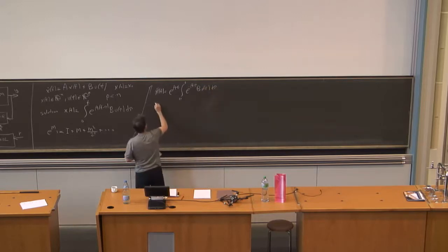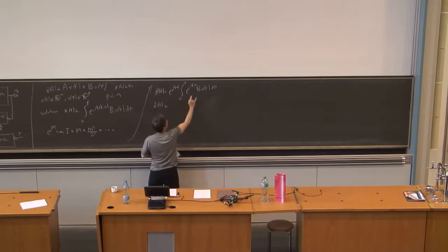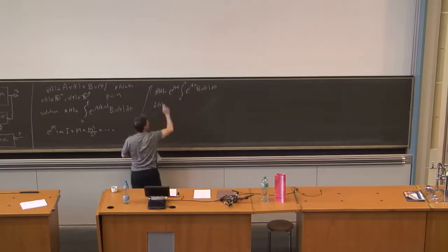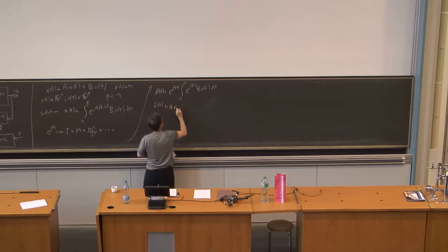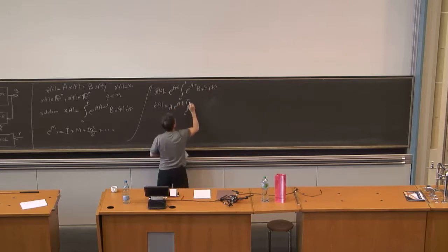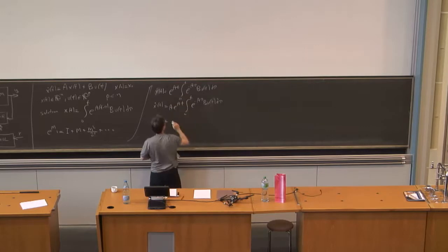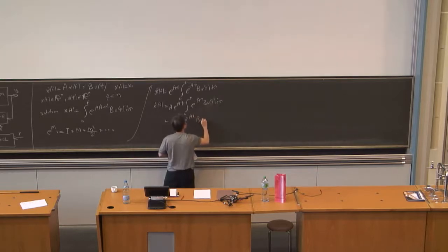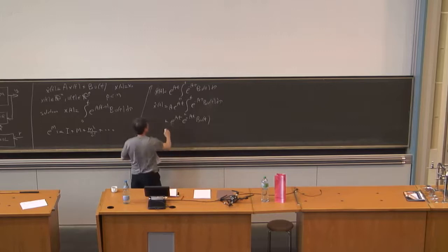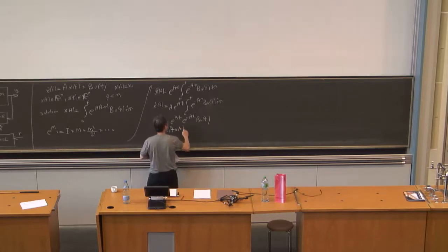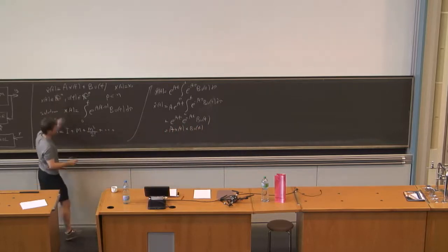So if I take the derivative of x(t), you have 2 terms with t: this term, and this term in the integral. Differentiate that, holding the integral constant: A e^(At) times the integral from 0 to t of e^(-Aτ) B u(τ) dτ, plus, hold that constant and differentiate the integral. That's easy. This is the integral, this is the t there, so I just substitute e^(-At) B u(t). And of course, this is equal to A x(t) plus B u(t). Okay, good. So simple sanity check. This is indeed the solution to this.